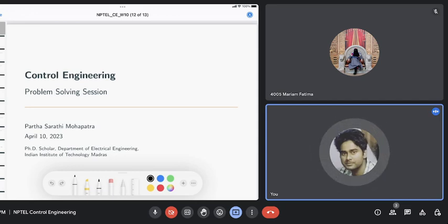As the name suggests, the minimum phase system will have the range of the phase plot minimum among all the types of systems which have the same magnitude Bode plot. Because of the presence of the right hand side zero, the phase range will be different from what is expected for the minimum phase system.